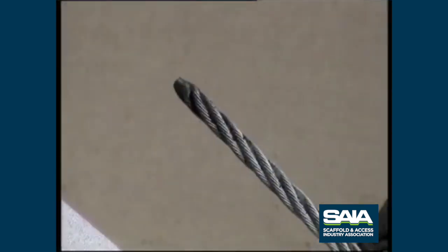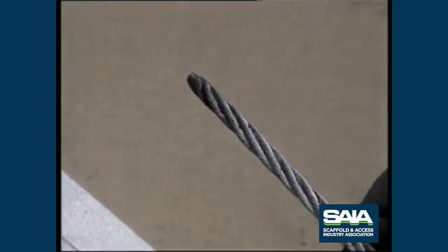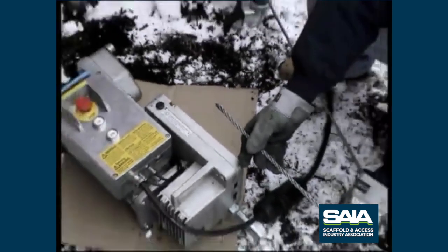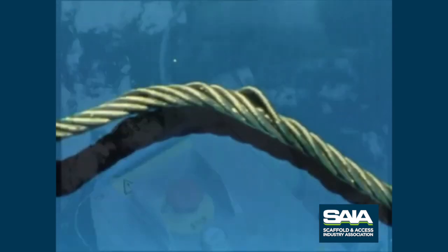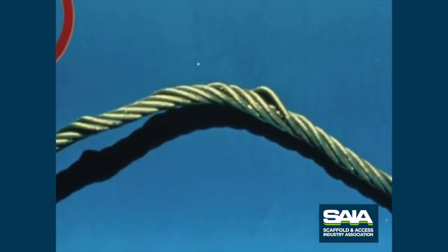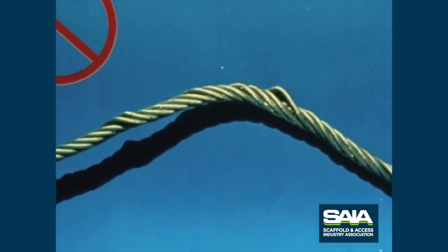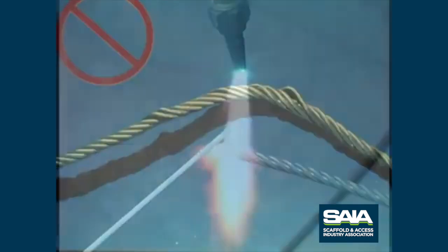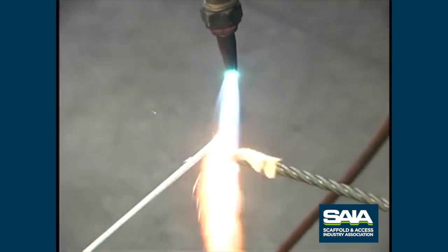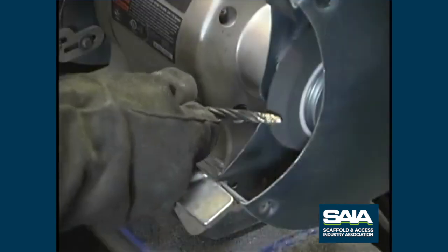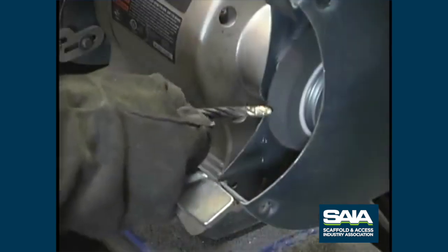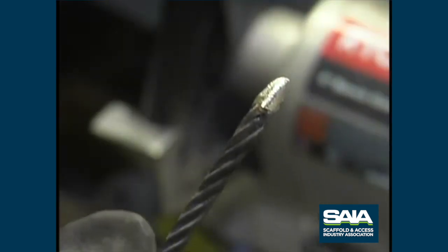Wire rope must meet hoist manufacturer's specifications. Diameter and construction are critical for safety. Distortions and bird cages are unacceptable as shown here. The tip of the wire rope must be prepared per manufacturer's instructions. Traction hoists must reeve the rope. A good tip is important.